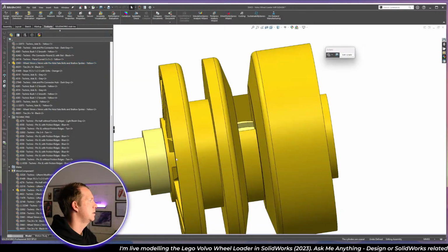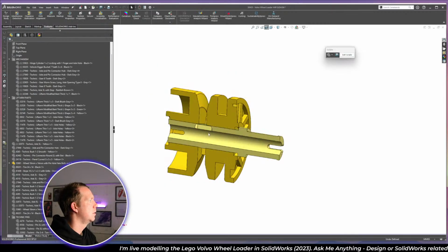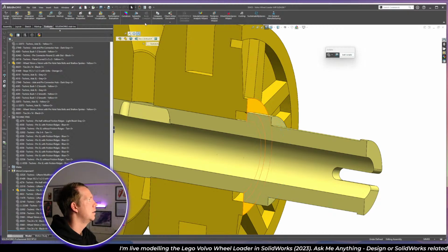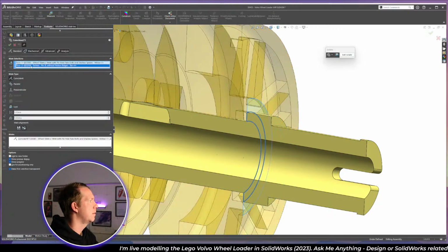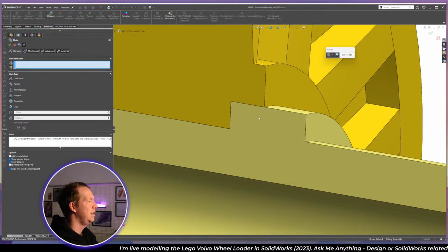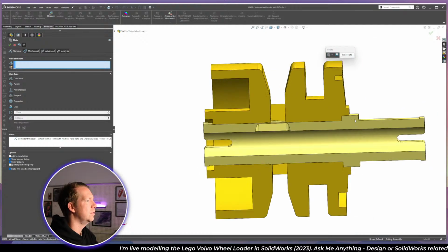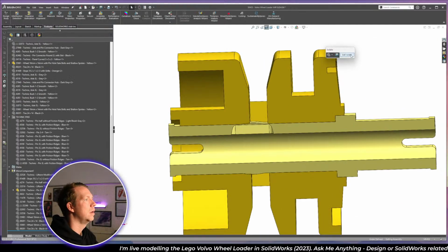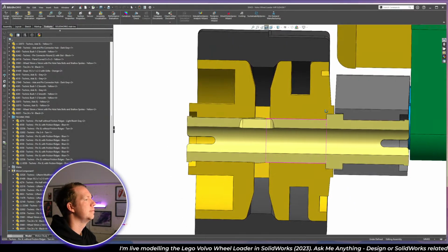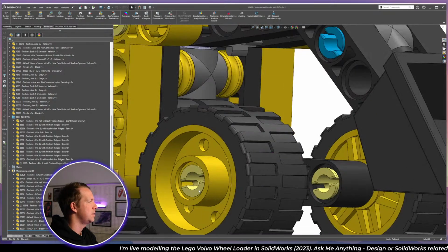These two pieces. Do a section view here, and look at this mate. Change this mate from this face to this face. Now that's a bit tighter than I would like. There should be some clearance there, but at least now this fits all the way through. That's all right. It's going to be the same on this side, probably.